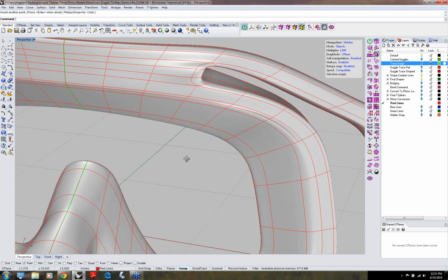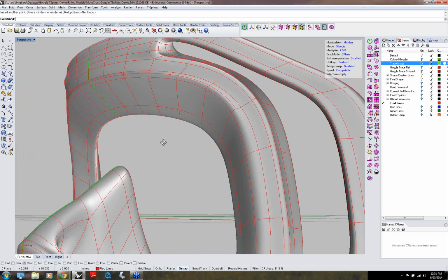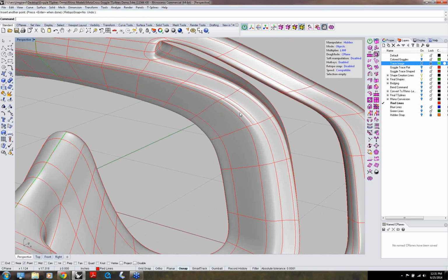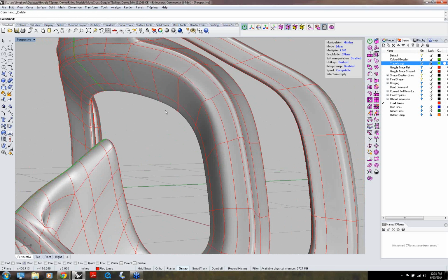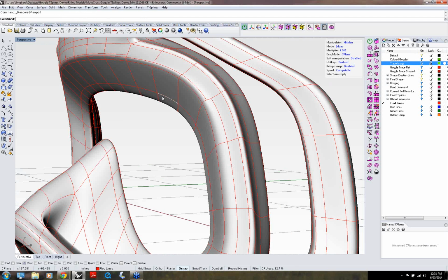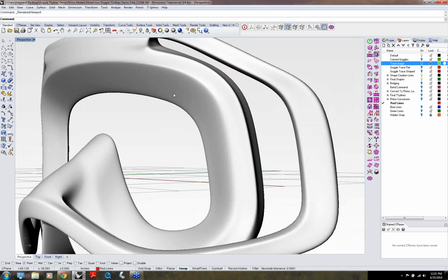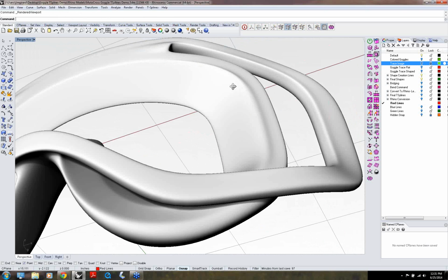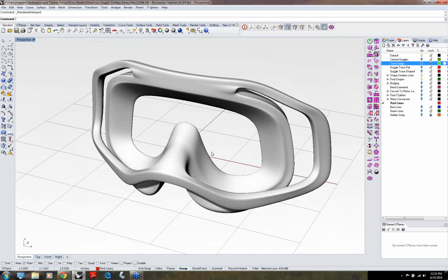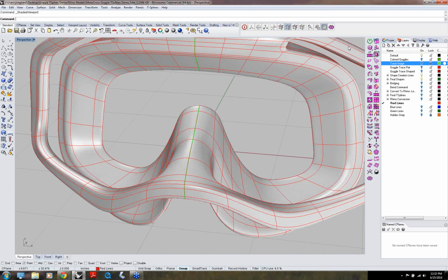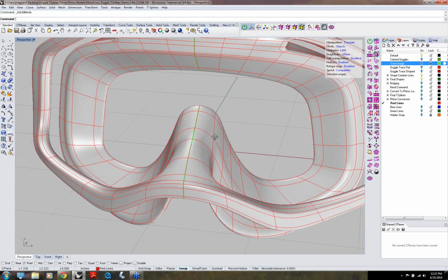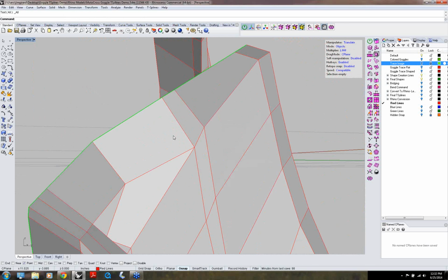And now you have a tighter edge there, but as it moves around, and you can say, well, like it's puckering here, so now you can say, well, I want to get rid of these then. And what you'll have is you have a tighter edge, and then it blends out to something smoother. So you can say, oh, geez, I'm getting sort of a bump here. So you go back, go to your T-Splines tab, take a look at what's going on, and say, oh, okay, I know what's happening.